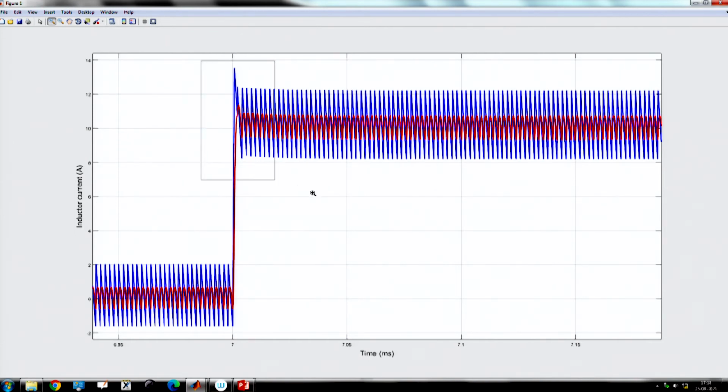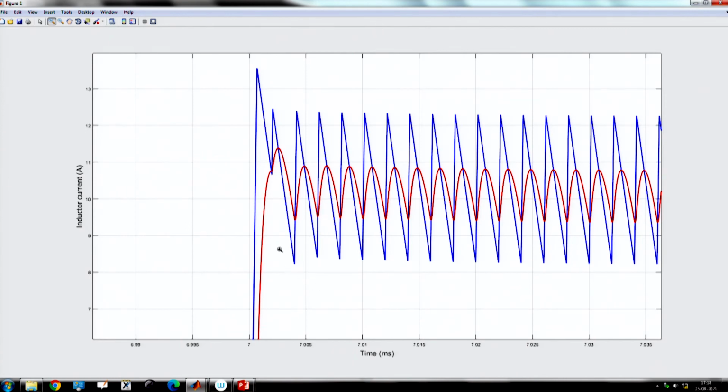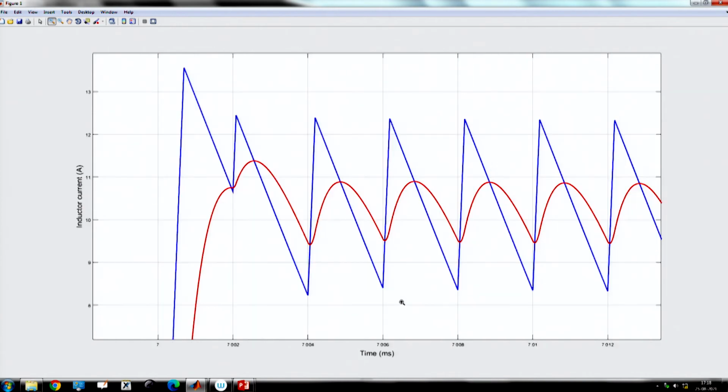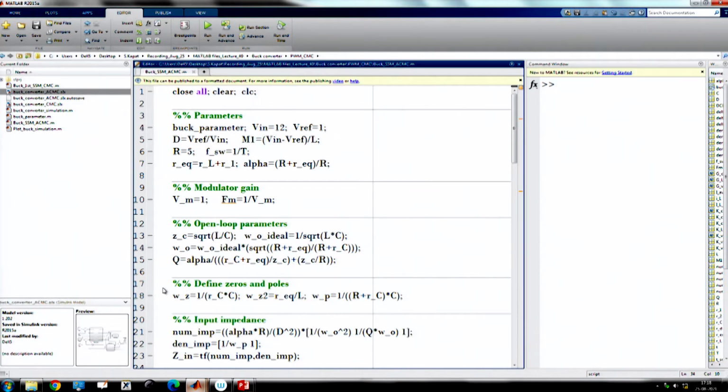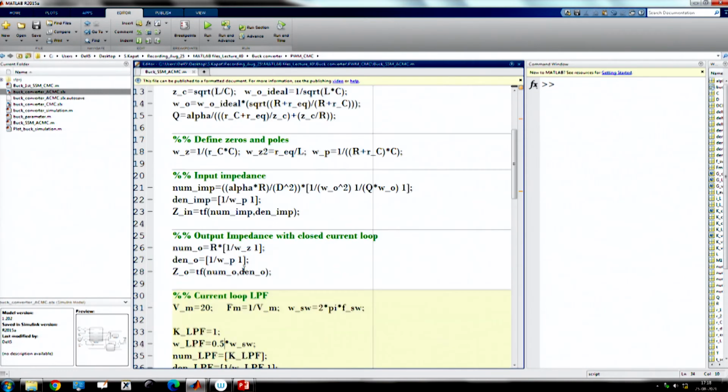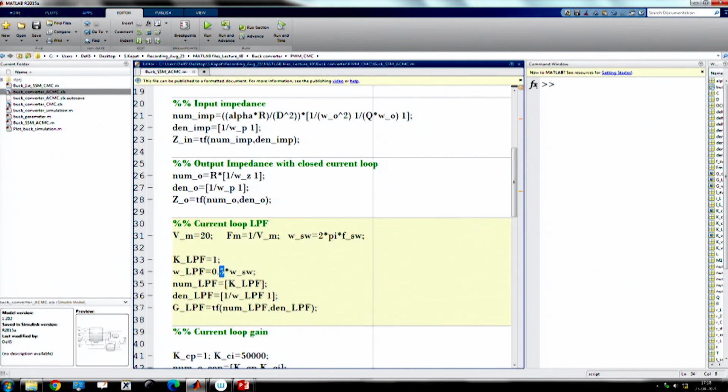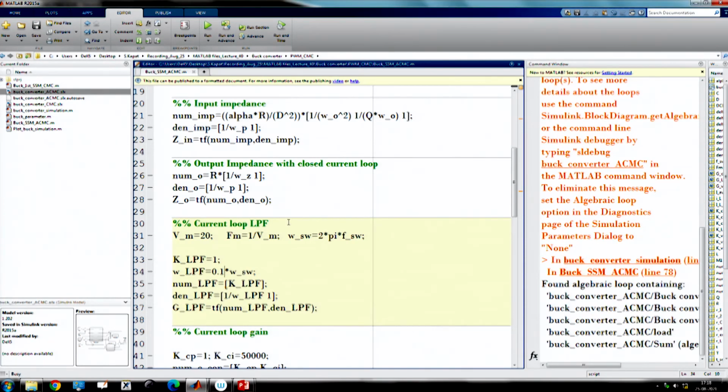So, it is important that the average current is maintained or not. It is maintained, except for this slow overshoot; it is more or less maintained. Now, I want to slow down the current loop. Let us say I take 1/10 and check the current loop. I have not made any changes in the current loop, and we will see whether it is going to respond or not.